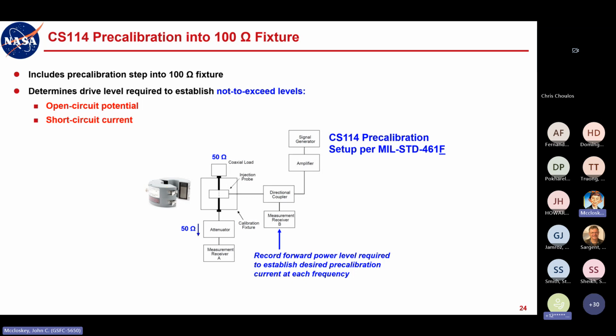And what is the maximum current that you can drive into a short circuit or very low impedance? Those are your extremes. So if you establish safe levels for those two conditions, anything else is in between, and you're keeping your hardware safe. All right. So that's the pre-calibration step per MIL-STD-461F.